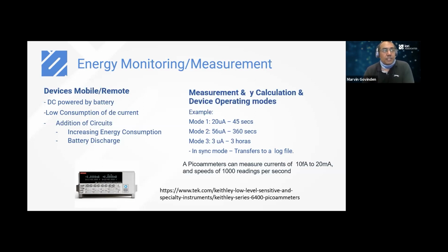So what we can do, if it's a device that has a certain behavior at certain times, it has sleep modes, it wakes up, when certain functions are on, certain parts of the circuit are on, is we can estimate the current. We can use, like shown here, a pico ammeter. We can measure how much consumption we're having on these parts of the circuit, and we can characterize it. And our system can be intelligent to know that once these functions are on, it times how long they're on for, and it estimates the power consumption. And that could be better in terms of battery life.